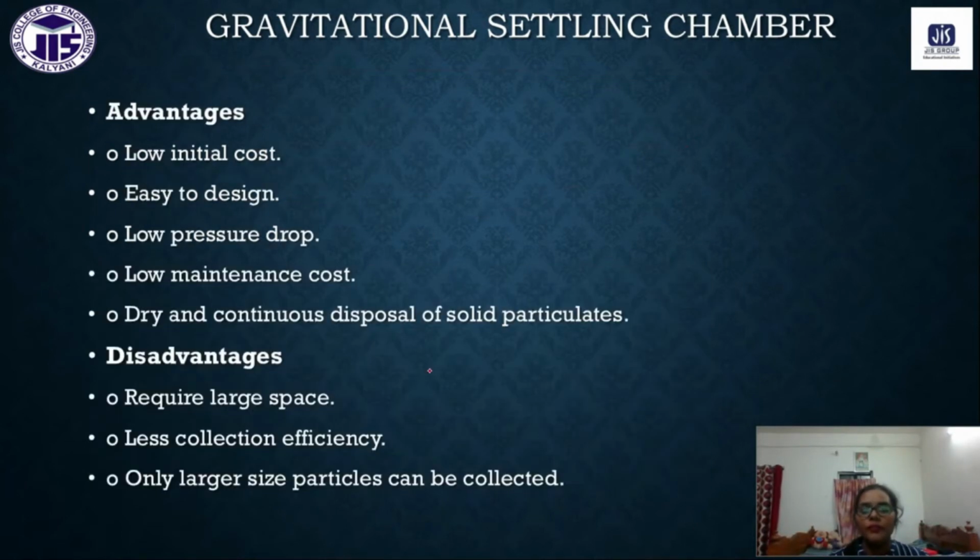What are the advantages and disadvantages of this gravitational settling chamber? It has a low initial cost, it is very cheap, and easy to design. The equipment is very easy to design, with low pressure drop, low maintenance cost, and dry and continuous disposal of the solid particulates. These are some of the advantages of using the gravitational settling chamber. But we still have some disadvantages also.